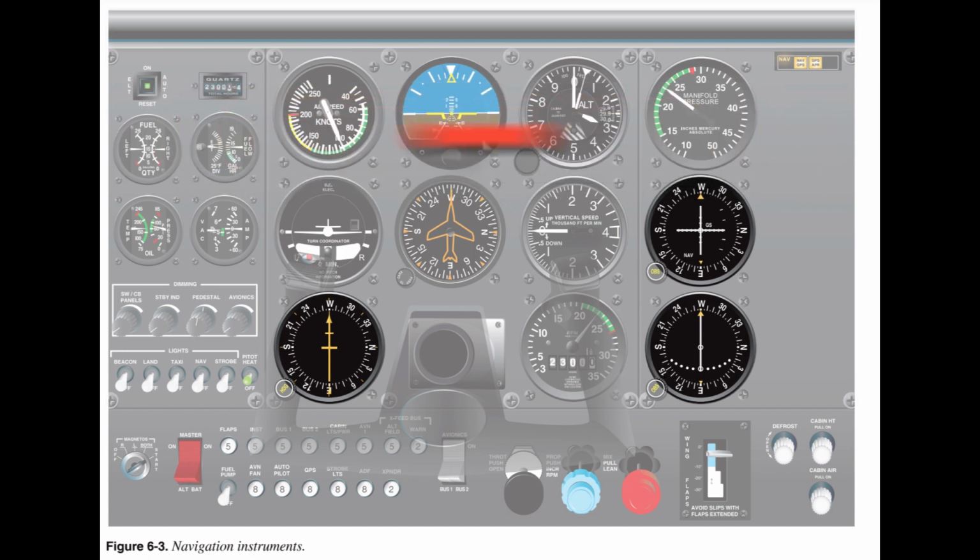Aircraft control during instrument flight. Attitude control. Proper control of aircraft attitude is the result of proper use of the attitude indicator, knowledge of when to change the attitude, and then smoothly changing the attitude a precise amount. The attitude reference provides an immediate, direct, and corresponding indication of any change in aircraft pitch or bank attitude. End of page 6-3.